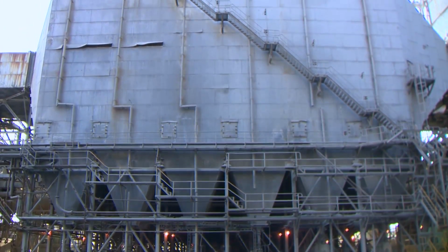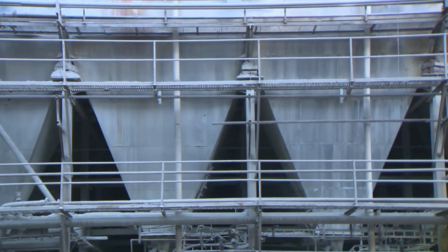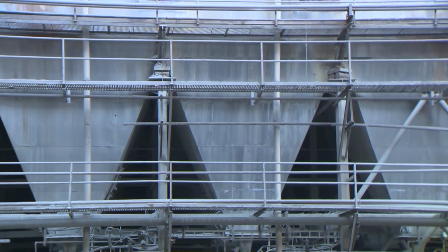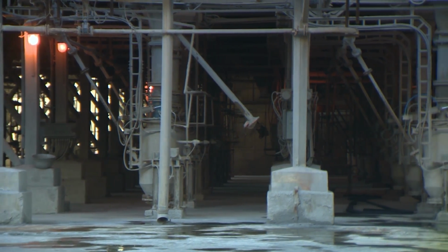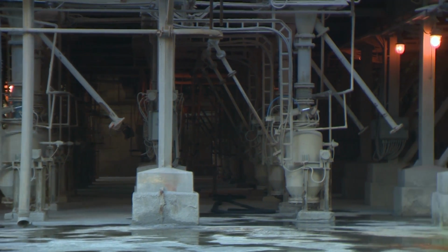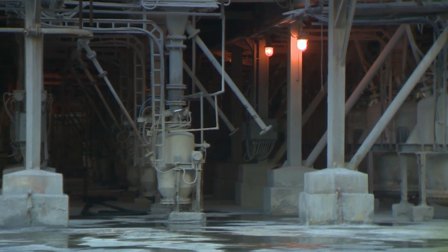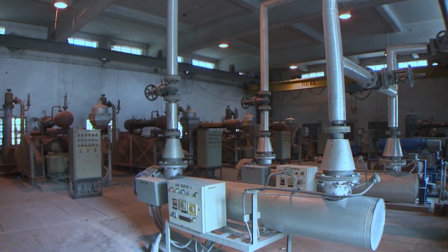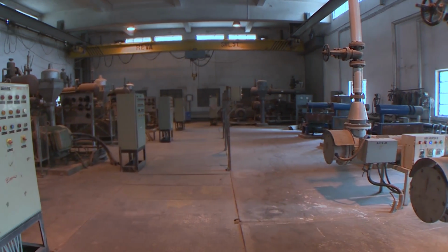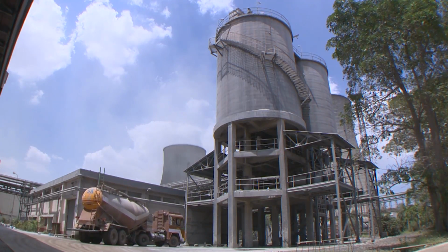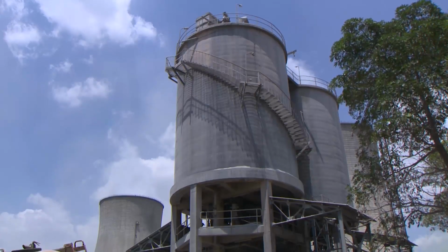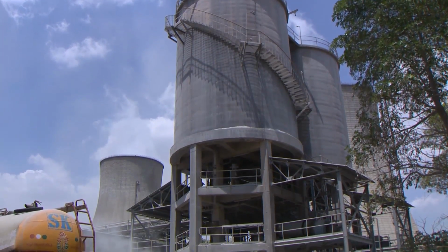At present, instead of wet ash collection, dry ash collection is adopted. In dry ash collection, the ash transporter receives fly ash from electrostatic precipitator hopper. Separate air compressors supply air for transporting the ash to the silos. From the silo, it is sent to the cement plant by closed trucks.